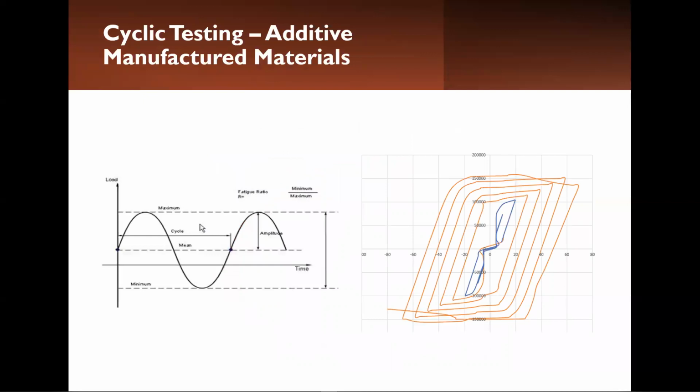All right, and then moving into the cyclic range, we are now looking at the ratio of the minimum stress to the maximum stress applied in a cyclic fashion to the material, known as the R ratio, which can be better understood by looking at this as tensile stress applied as the maximum stress value, and the compressive stress then applied as the minimum, over and over to the material within one cycle.